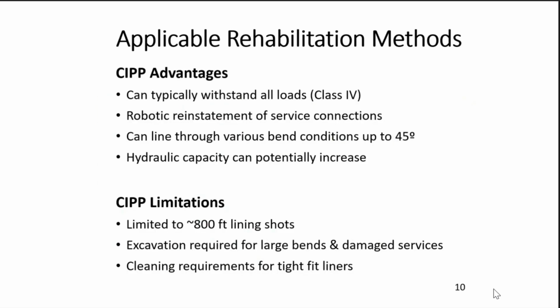So some of the benefits here, you can design these liners. So we're not putting a new pipe in there, right? We're building a liner inside of the pipe. They can be designed to be fully structural, withstand all internal and external loads. They can also be designed to be interactive.